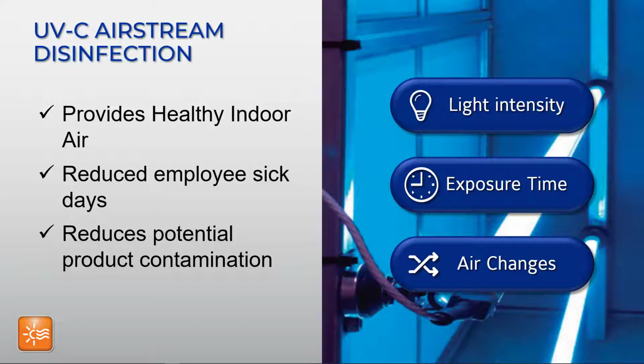It's good to note that having room in the unit helps this style of system. The retrofit performance is based on a 40-inch spacing downstream of the cooling coil, which is pretty close to standard for our mixed air units. But just how effective can UV airstream disinfection be?